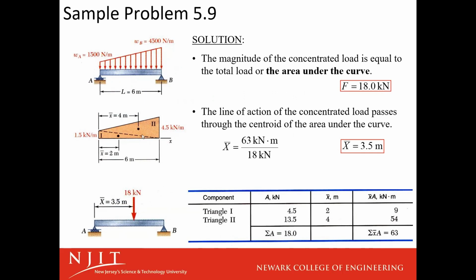Kilonewtons per meter, we're multiplying that by meters. We're getting units of kilonewtons. That's our point force equivalent to that distributed load. That point force is going to be applied at the x-centroid of this whole shape.